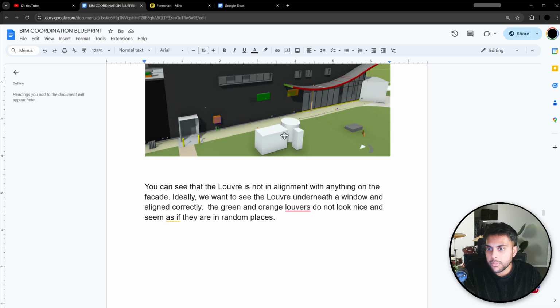But it wasn't like that because it was not designed properly. So the mechanical contractor eventually has to just go off the design, and they place it like this, and then it's set in stone, right? And there's also limitations with the units. The mechanical unit, like air conditioning units, might not be able to be upsized based on if you're adding a lot of bends, it increases the unit size, you have to lower ceilings, all these issues come into play, right? So that's not something that you really have to deal with as a coordinator.